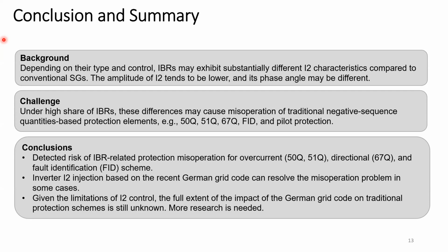The second question is, if there is a negative sequence voltage, then the negative sequence current needs to be generated, and this will most likely have some delay. So I think 30 milliseconds are specified for that. So question 2 is, are the controls fast enough to guarantee dependable and secure negative sequence element operation in traditional tripping times, 1 to 1.5 power cycles?